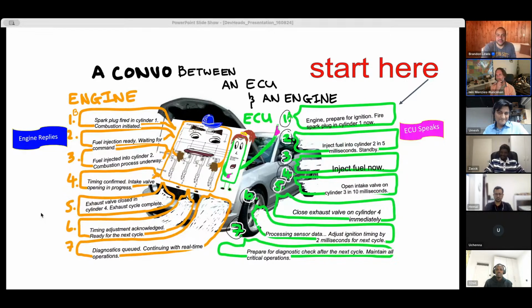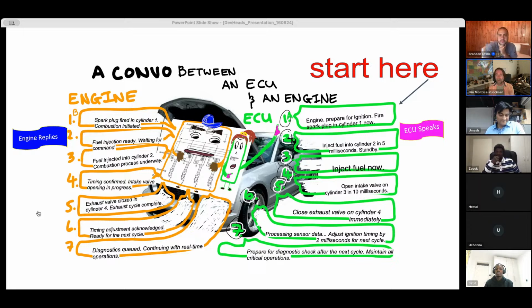What I'd also be looking at is how many things are you scheduling? If you've only got 2 or 3 things, writing a simple scheduler, yeah, that's easy enough. The more complicated your system is getting, I work on the concept that there has been a lot of research put into schedulers, deterministic schedulers, how to create them, by people far more intelligent than me. So I'm going to leverage their ability when it starts getting into 10, 20 things I'm scheduling. With that amount of complexity, I want to have a beefy scheduler.